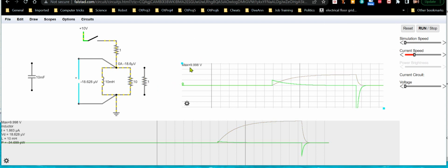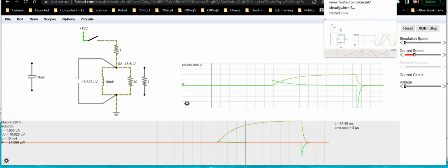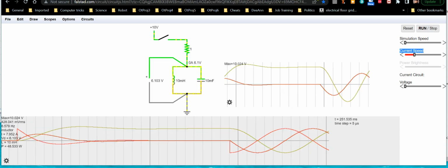That's what it does. That's why if you have an inductive load and you open up a toggle switch, it'll arc the switch. In fact, your switches aren't ready to handle those arcs, and it'll eventually eat up your switch. Those inductive spikes, that's where it comes from. It'll generate whatever voltage it needs to try to maintain whatever current's flowing through that circuit before the switch is open. And if that means it needs to create a 10,000 volt arc, it'll create a 10,000 volt arc. So you've got to remember that. Those can be serious issues when it comes to practical real world electrical circuits and systems.